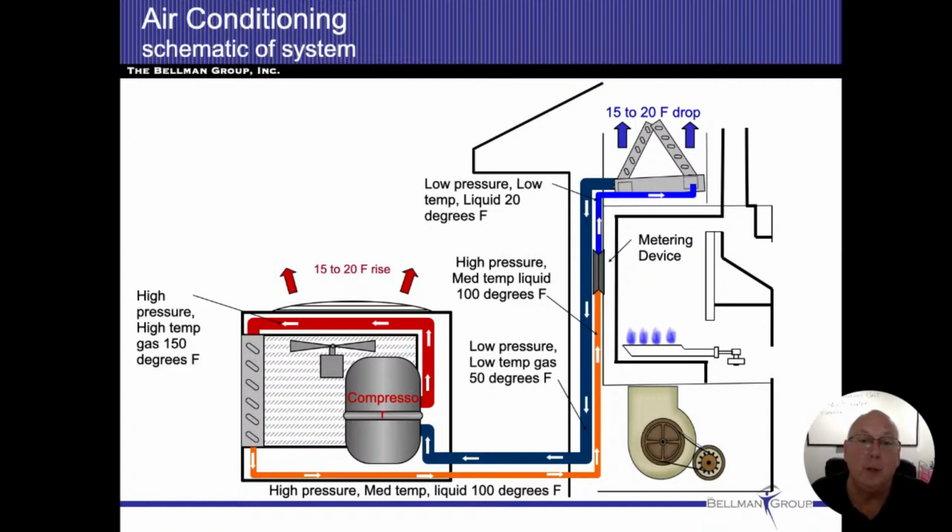on. If you look at this kind of carefully, you'll see that compressor, and I'm not talking about the fans that go ahead and blow the air over the coils. The compressor is really the only moving part of the air conditioner. So as I'm adding pressure into the system, I'm also releasing pressure at that metering device. And those things are supposed to be in tune perfectly.